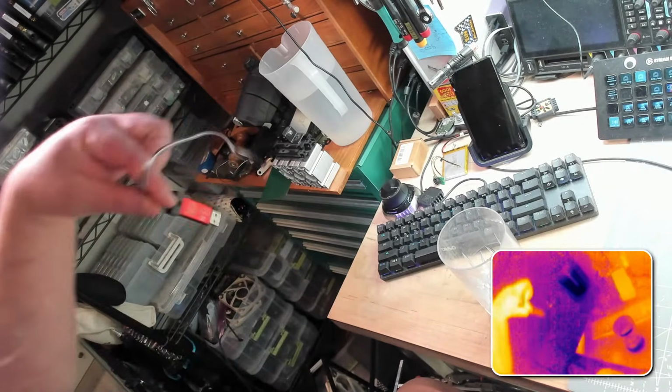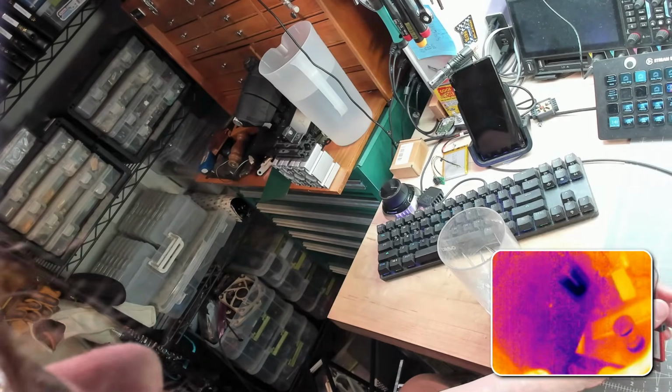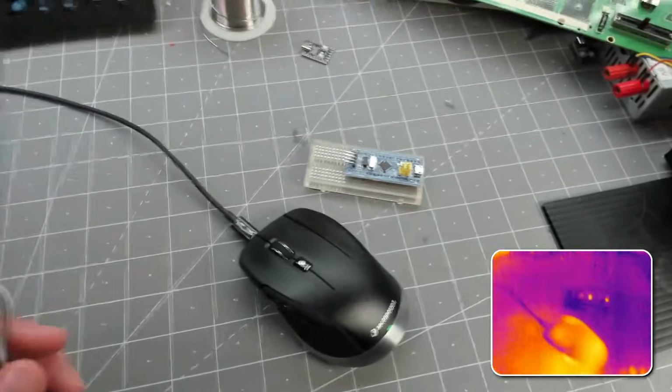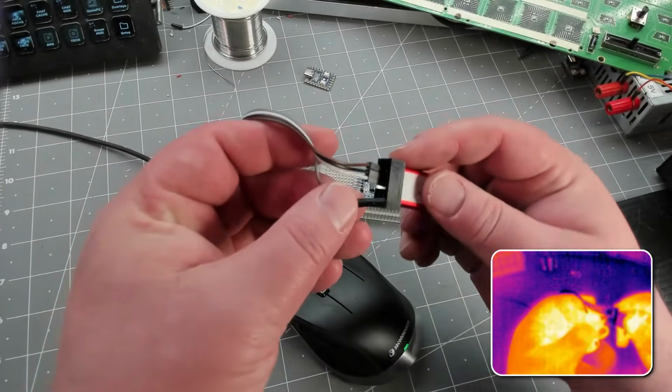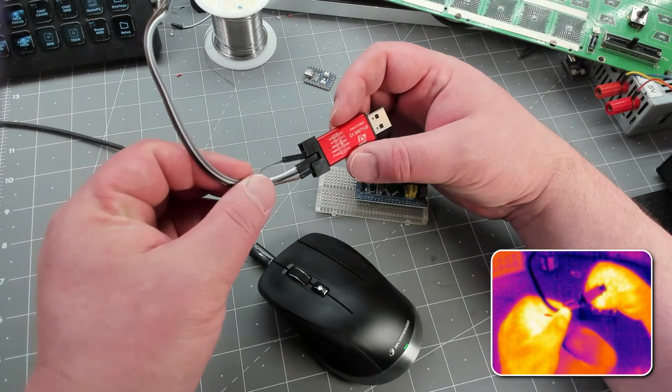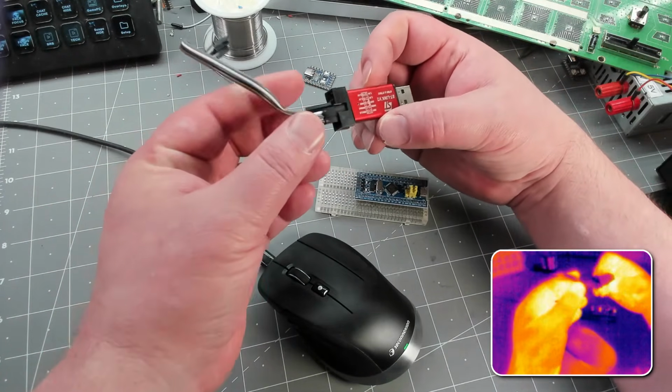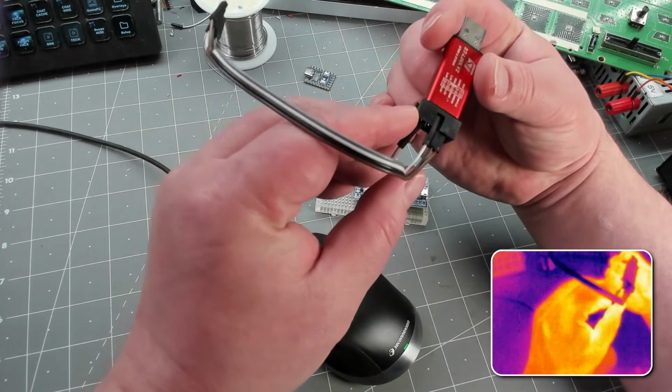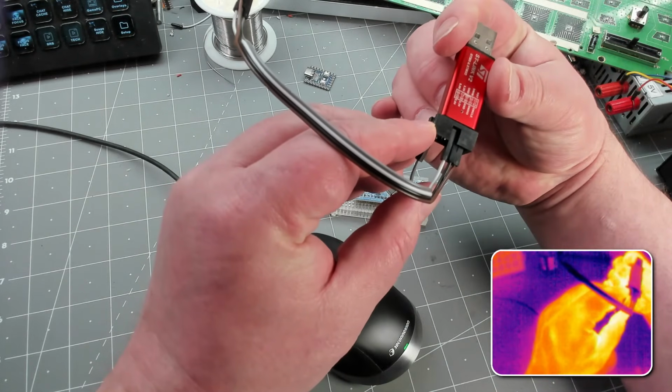Here's the ST Micro clone. These things are very, very cheap. Yeah, we're going to try, the first thing is getting a blinking LED. So we need 1, 2, 3, 4. I got 4 here, that's good. We need 3 volts and ground.